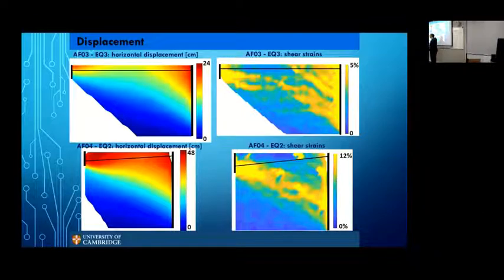In the first case, the highest displacements are happening just behind the wall, anchor wall, and behind the main wall. Whereas for the shorter case, we got this whole thing moving. Those are the equivalent shear strengths. Ignore those for now. So if this is what's going on, we can clearly see that that is what we call the local failure mechanism at the start, and this is the global mechanism. So we are able to capture exactly what is happening in the field using the centrifuge test.